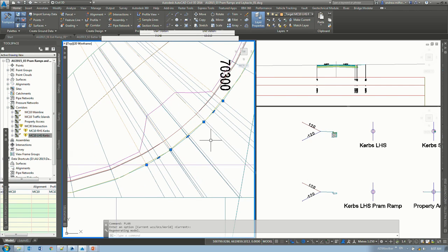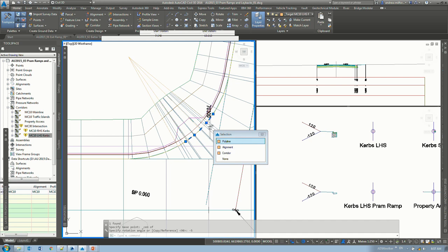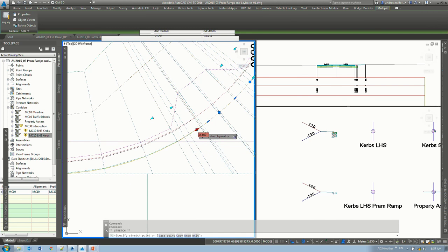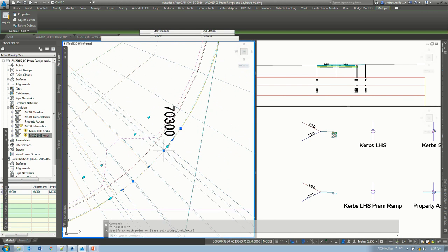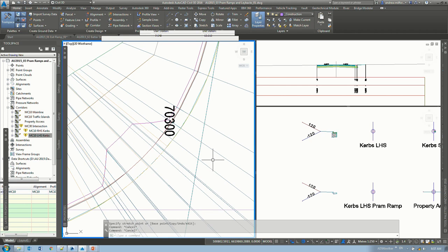So to actually move them around, all I'm doing in this case is I'll take this polyline and rotate it around the center of my curb return there. I'll say rotate, say, -5 degrees. All I do is pick this up, select that and snap it to there, and take that point, snap that up to there. So that's how easy it is to manipulate and move it after the fact as well.